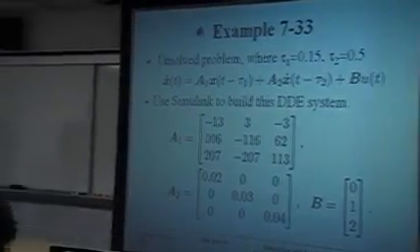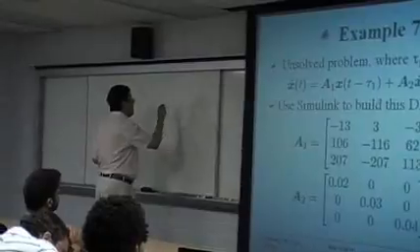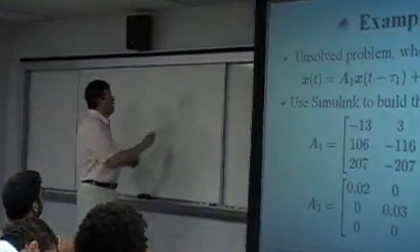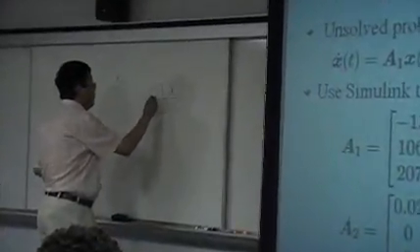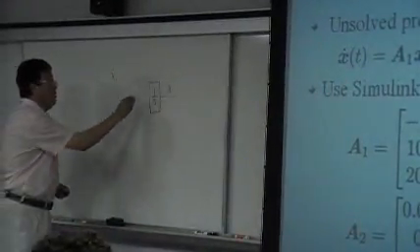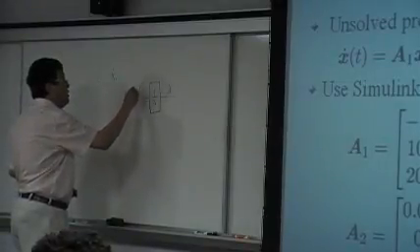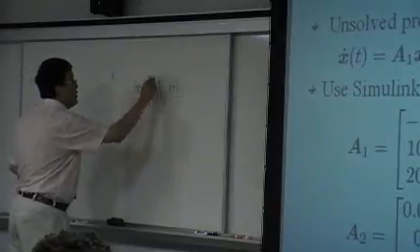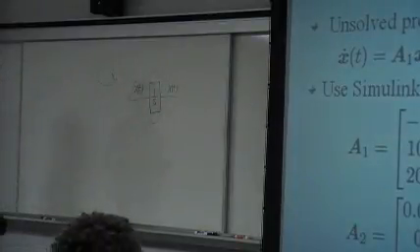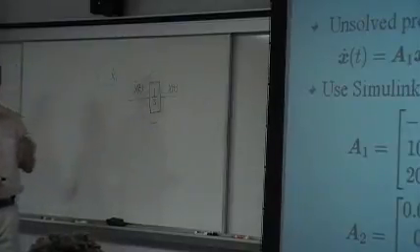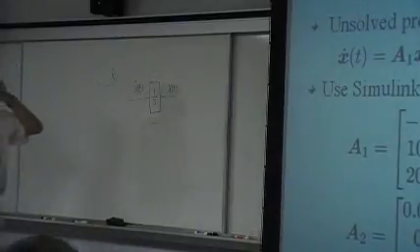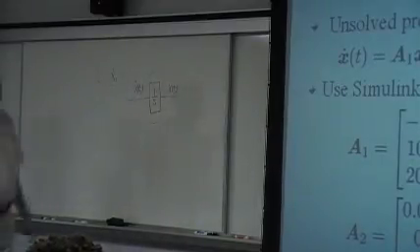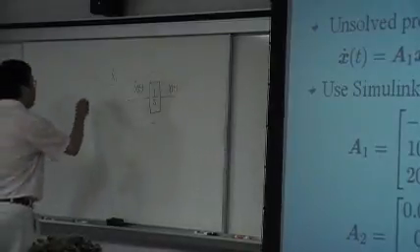Again, we have to define the signal x here. Here x is a vector. And once we have defined the x, then if we introduce the integrator, we will have x dot at time t. So we will see that this block can be used for scalar signals as well as vector signals. So this is the signal of x. And this is the input signal u.